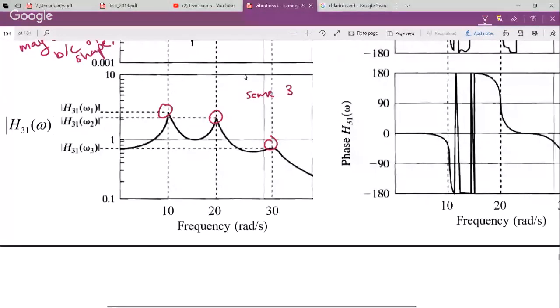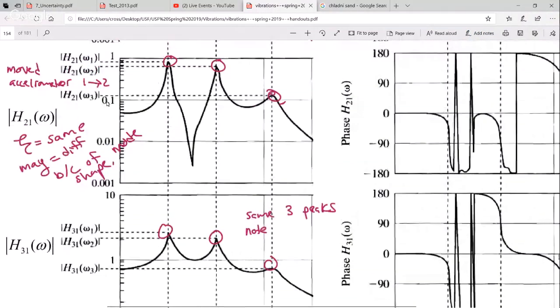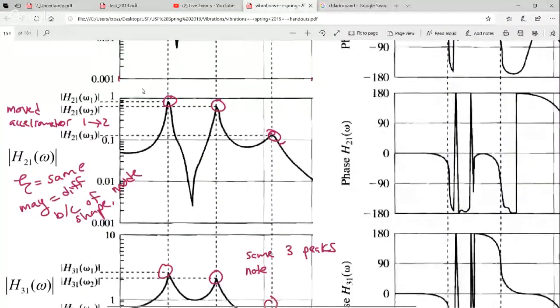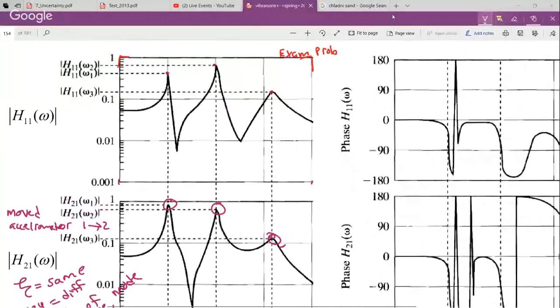All right, so let's take a look at this for a minute. I'll get you guys to write it down so I don't have to go over and write stuff down. Let's just take a look at the first mode. This would be the first mode. Why? Because it's the lowest frequency, right? Ignore the data over here for a minute. Let's look at this right here. At this first frequency, the magnitude here is what? 0.2, 0.1, 0.2, 0.3, say 0.35. Close enough for what we're trying to do.